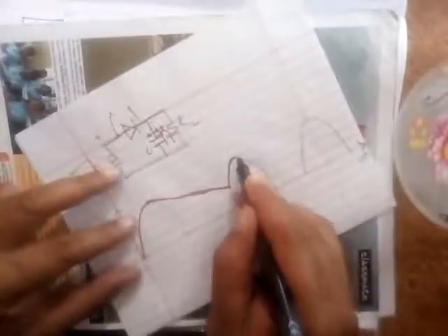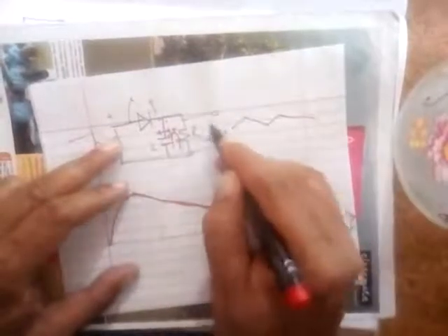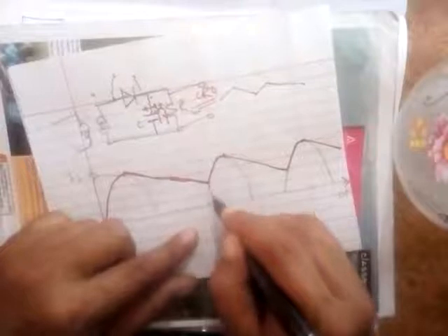Now further, again this becomes forward biased and it charges to the maximum value, and further it discharges. So let's read it this way. You will get a triangular wave at the output if you apply a CRO at this point. So this is what happens in the case of a capacitor. Is that clear?